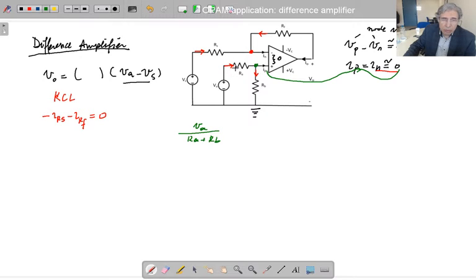That current is also equal to this current, since this current is equal to 0. So if I multiply this current with that RB, I'm going to get this resistor voltage, which is the node voltage of that green. On the other hand, I know that this node voltage is also the same as this red node voltage. So I'm going to multiply this one with RB. So altogether this now is this node voltage. At the same time, it is this node voltage.